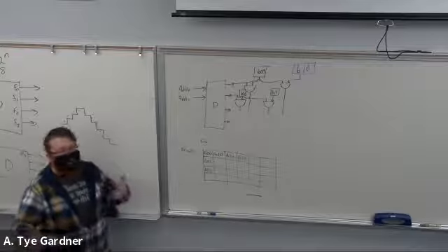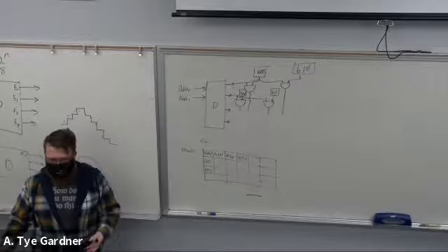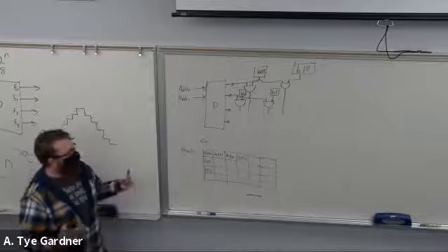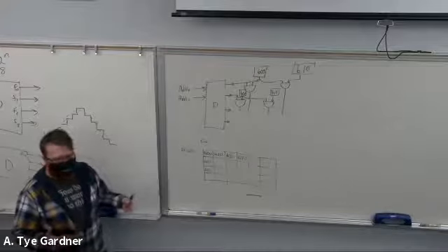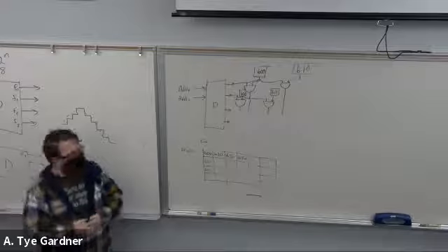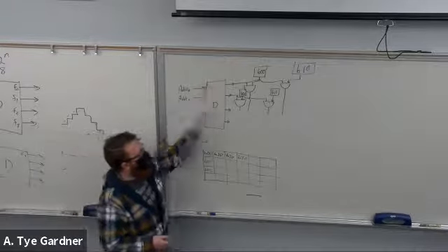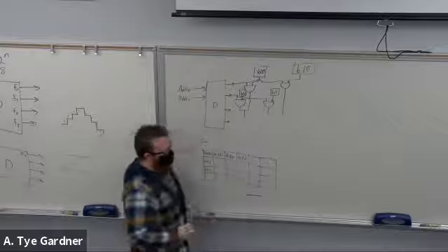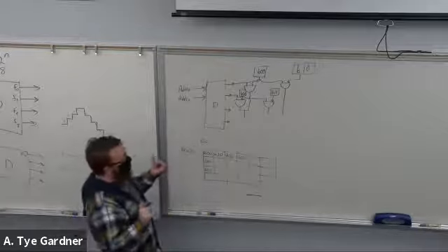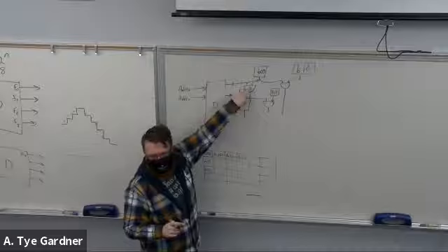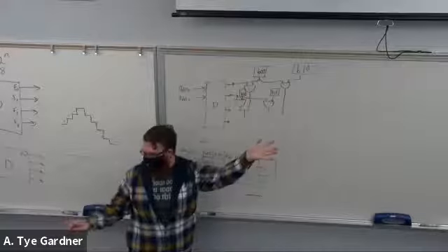Okay, so what we want to avoid is what we call multiple drivers. We don't want it to freak out and say, oh my goodness, we could run into a situation where there's multiple drivers. Now, we know that that's not possible, right? Because we know that we designed this to be 1 hot, and so we could probably just hook these AND gates together and call it good, except for the fact that they're AND gates, and this one could be outputting a 0, and this is outputting a 1, and now we broke it, right?